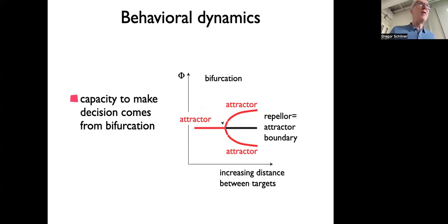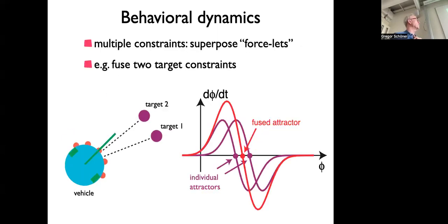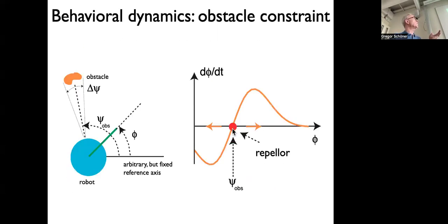That's a good question. I was going to answer that in the context of obstacle avoidance. You could ask that same question for obstacle avoidance, right? You could ask, why turning rate 0 when you're heading to the obstacle? That would mean if you're almost colliding, you have a very small turning rate, and then you accelerate, while if you're this distance, you have a large turning rate. So why not make it a jump? Like have a very strong turning to the left angle and then a very strong turning to the right angle. A jump like that would be better than going through 0, right? That's maybe the question you're asking now about the analogous thing for the attractors.